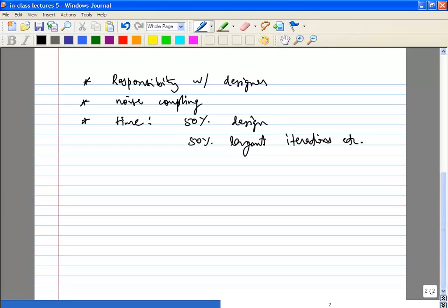Okay, so let's say you're going to design an LNA and you're given, let's say, 3 months to do it. You'd probably spend only 1.5 months designing, or maybe 1 month. So first you'll start off with looking at what architecture is appropriate, then you'll try simulating it, and finally you'll come up with a good design. Then finally what you'll find out is you lay it out, then there is a step where you actually find out how good the layout is, and we're going to talk about that today.